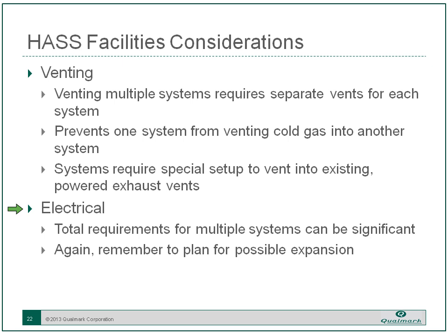Take a look at what's specified. That's a good way to get an idea of the efficiency of a chamber and how much it's going to cost to be running it, by looking at what the power requirements are, the input power requirements. So keep that in mind as you are looking for a chamber to do HASS in. And as long as you're running all those big fat wires, it might make sense to run enough for a third chamber if you're running for two, because it's cheaper to do it then than it is to add it in later.